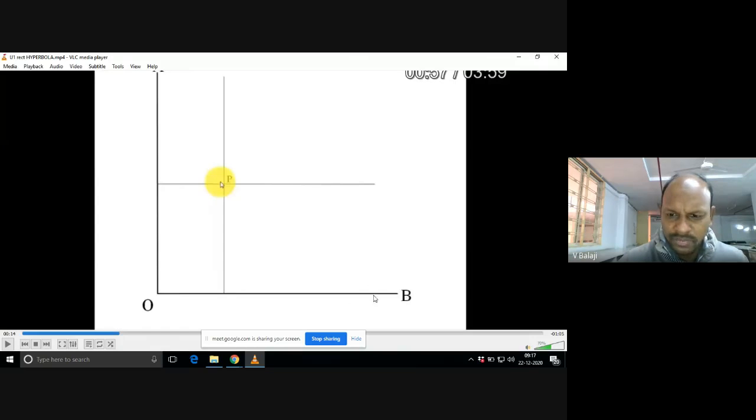While drawing this OB, match your mini drafter scale to the border line of the drawing sheet. The already printed border lines will be there. You match the drafter scale to the printed border line, parallel to that, and start on the drawing sheet somewhere OB. You need to draw the OB line of any length with an HB pencil. Similarly, tighten the mini drafter knob parallel to this OB.